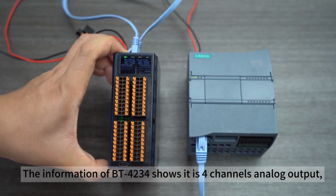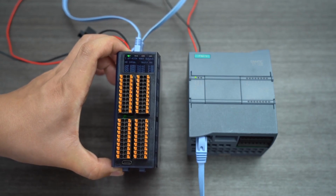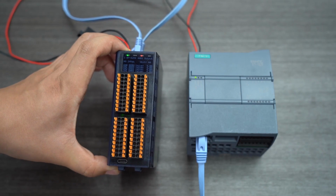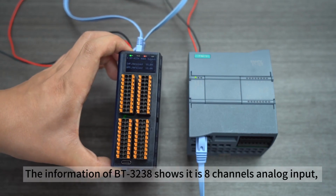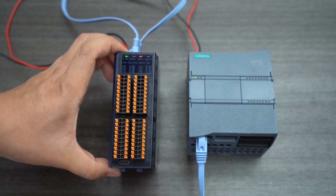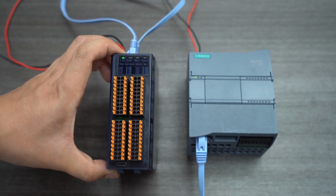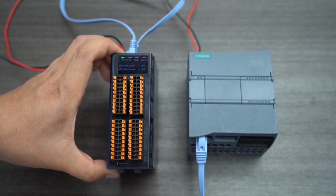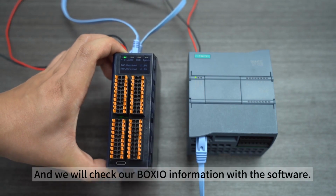The information of BT4234 shows it is 4 channel analog output, and you can see the value from channel 0 to channel 3. The information of BT3238 shows it is 8 channel analog input, and you can see the value of the 8 channels. Now we are back to the initial status of the LED screen. And we will check our BOXIO information with the software.